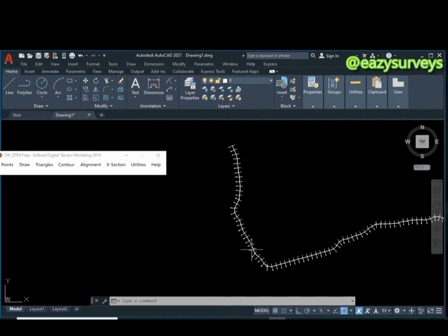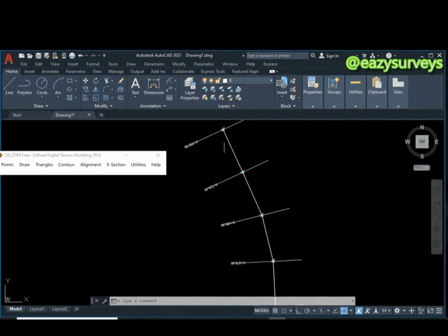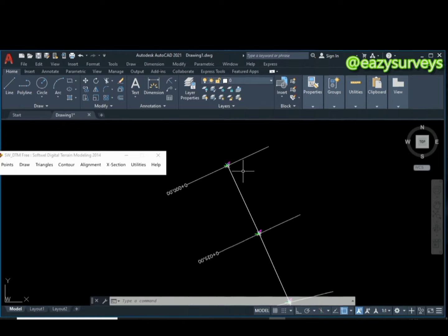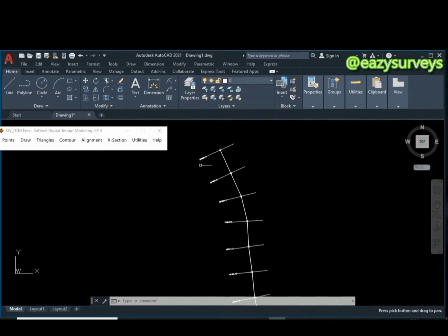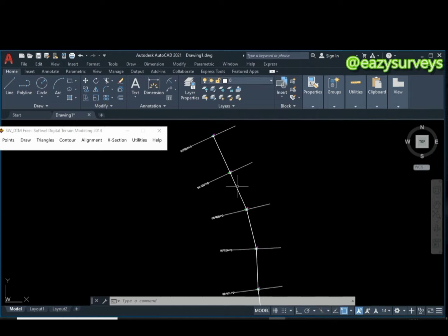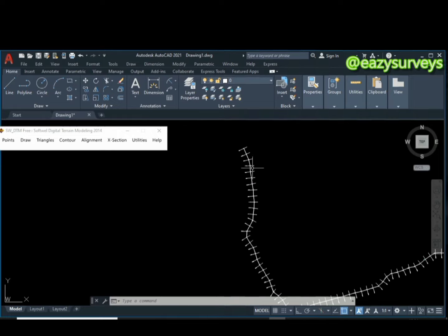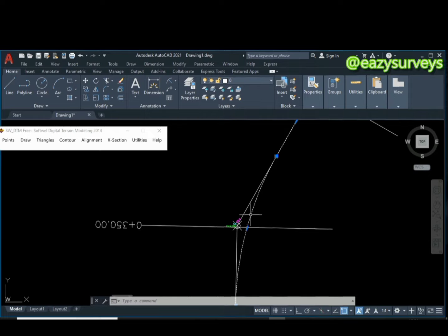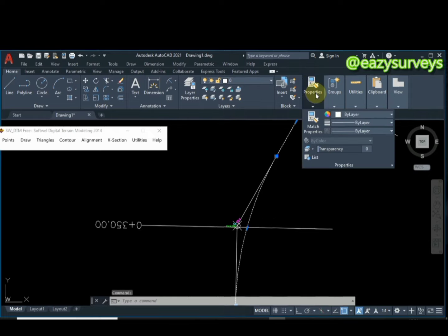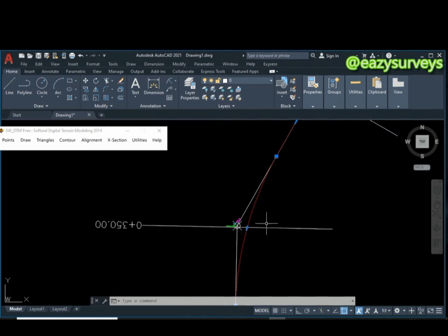All right, so the next thing we are going to do is to professionally decide the width of our roads as well as the gap between them. This is based on professional judgment as well. So via my own judgment, the curved alignment, not the initial one, I'm just going to make that one red for easy identification. So you come to properties, then scroll to by layer, then make that red. So this is actually the curved one.